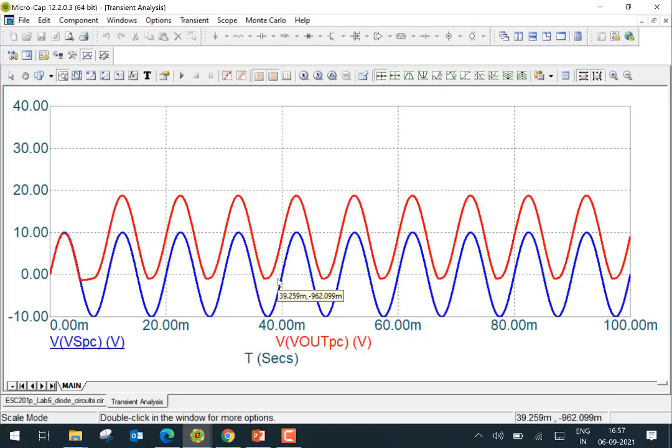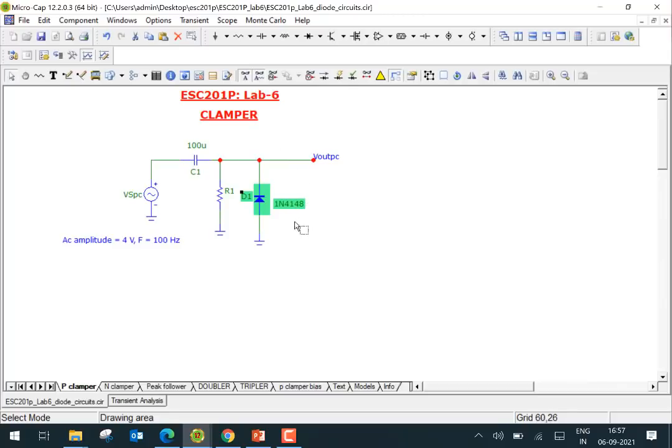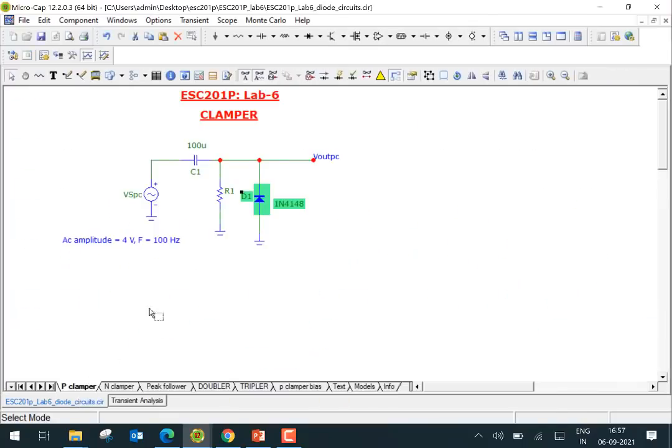So, as we said, you can explore the impact of a resistor here. You can try and understand the operation of this circuit by looking at what happens in the positive cycle. For example, you see here that as you switch on, it goes here and follows here, and then this particular part, and then it shifts up. So how does this actually happen? During the positive part, of course, the diode is off, and this part of the circuit is acting here. The time constant chosen is such that the capacitor is not able to charge.